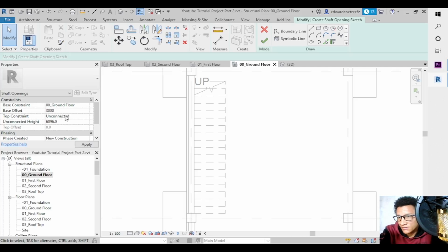So your base is 3000, and from your first floor, the top constraint will be extra 200. Let's make it 500. Let me say apply,